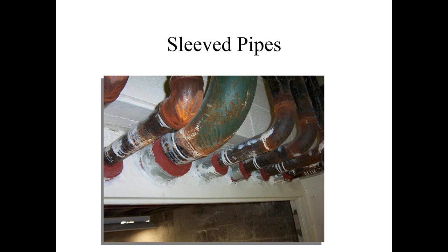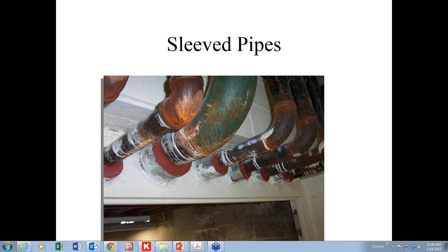Secondly, the fire resistance rated assembly was tested with the Firestop product smooth and adhered. It wasn't tested as a spaghetti mesh all over the place without adhesion and with maybe gaps. So the smoothing is required because it was mentioned in the Firestop manufacturer's installation instructions. If it says to smooth it, we've got to smooth it, period. Really great question. Thank you very much for asking that.